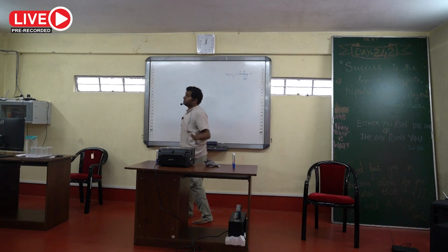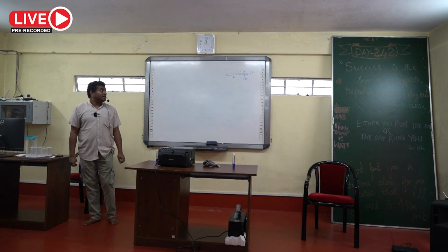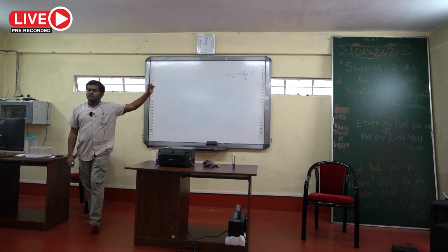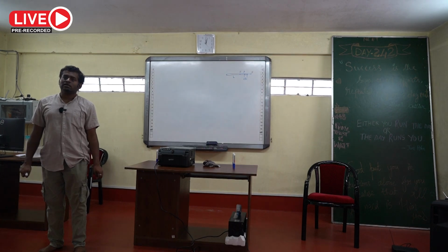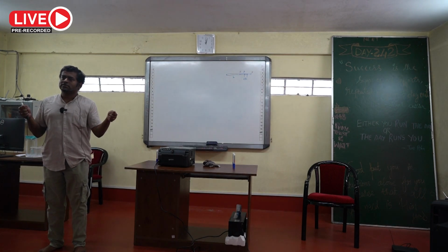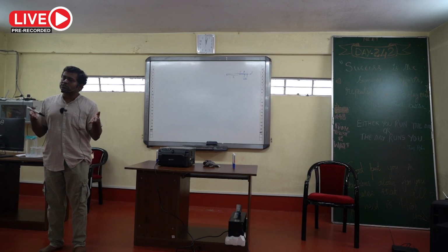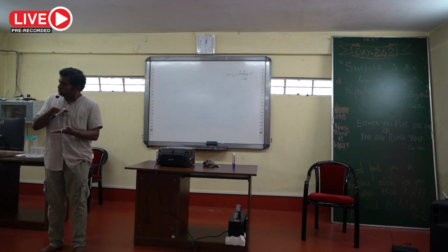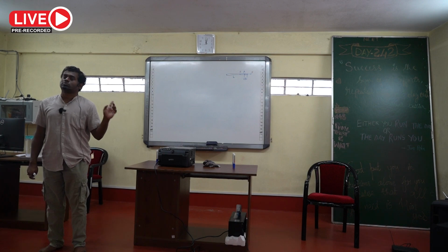What we have ignored previously when we were defining Young's modulus is that if the wire is very thin, then you can neglect the change in diameter when you are changing the length. Length is increasing, so total mass or volume remains constant, so diameter should decrease. Area of cross section will decrease, diameter should decrease, but we neglect that when we are defining the Young's modulus.